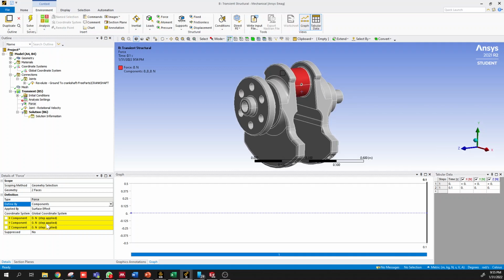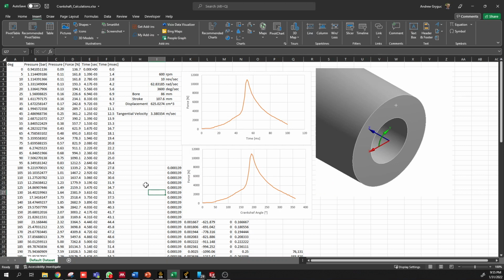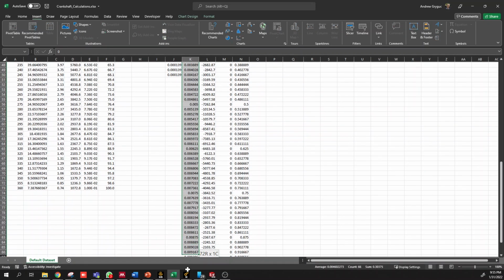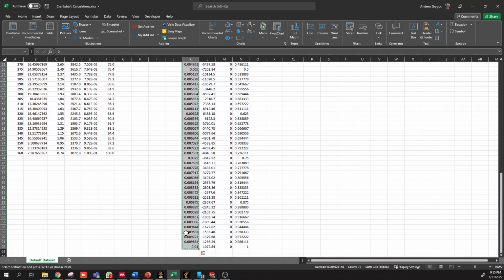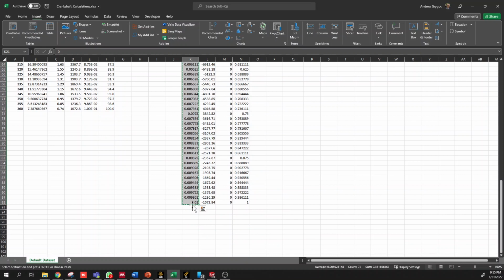So now what we want to do is, you can see on the right, because it's a transient analysis, we can input tabular data here. It auto-populates 0 for everything for the very first part of the analysis and the ending of the analysis, which is 0.1 seconds. So taking the data from this curve, I have some cells here that I'm just going to copy in. This is the time varying between 0 and 0.01.